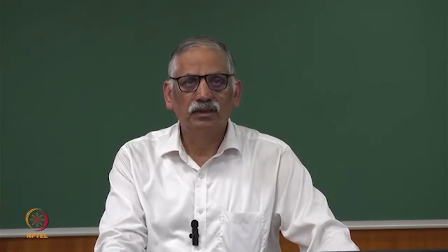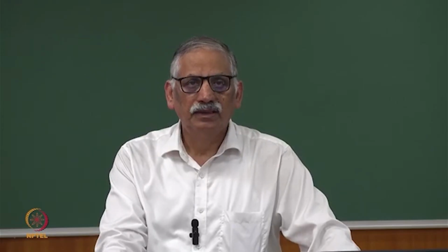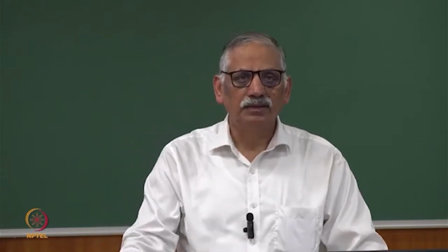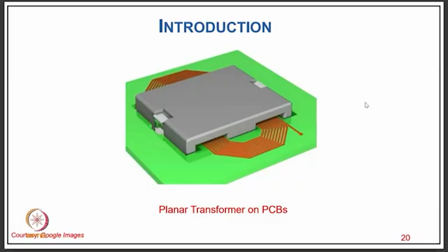So there are also such transformers. The very purpose is not only the isolation but providing the phase conversion also, and providing phase shift also with the help of the transformer. So there are plenty of applications of this transformer. In those applications, of course, we have planar transformers which we use on PCB for electronics applications.